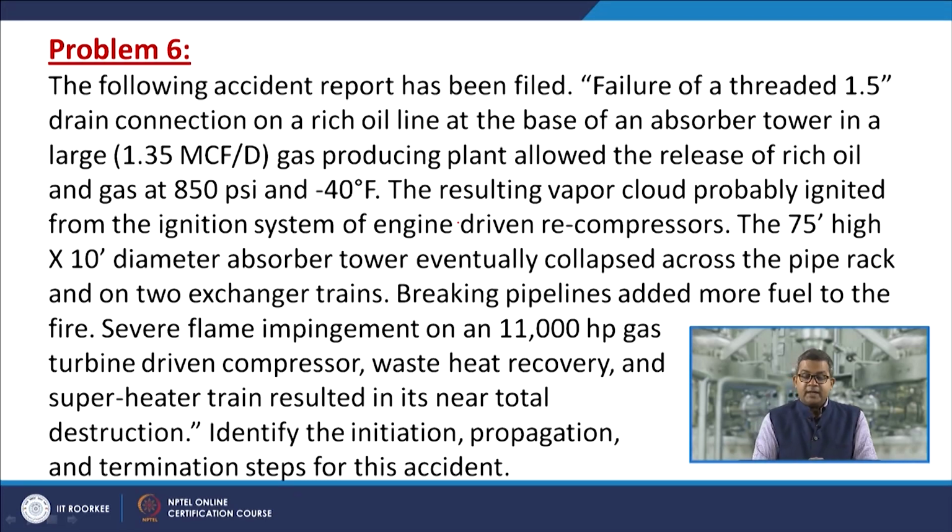Propagation: once initiation starts, let us discuss the propagation. The release of rich oil and gas, the formation of a vapor cloud, ignition of that vapor cloud by the recompressor, and the collapse of the absorber tower across the pipe rack. So, this is the propagation, and of course, the termination is the consumption of all kinds of combustible material present within the plant periphery. By this particular problem, you can have a look at the different aspects of initiation and propagation.